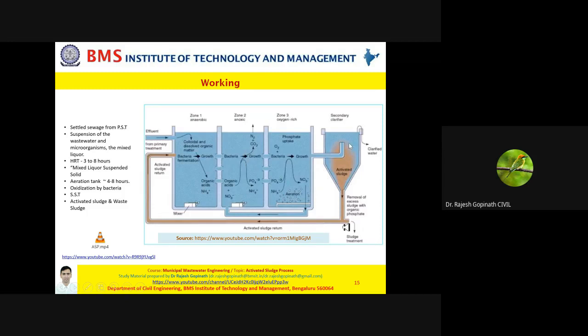So from here, where your wastewater and your microorganisms were kept in suspension, after the treatment the wastewater enters into the secondary clarifier. Now, what happens in the secondary clarifier? Here a detention period is offered, and based on this detention period, sludge formation takes place.